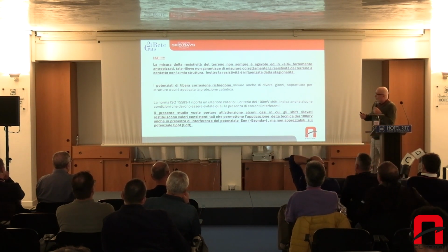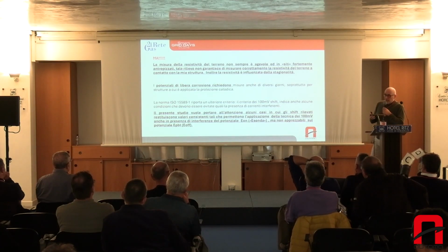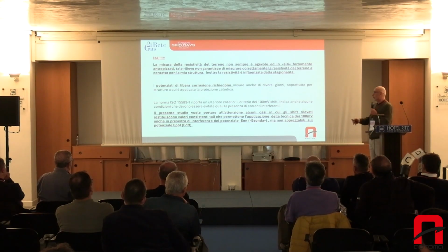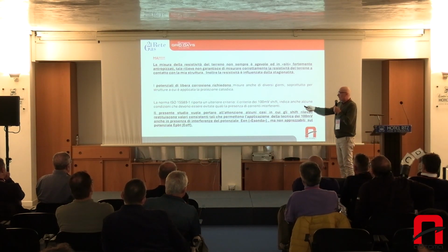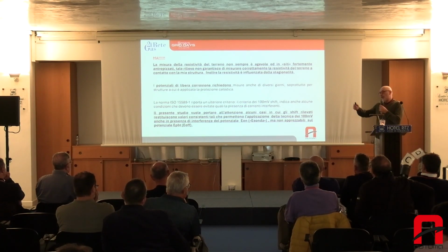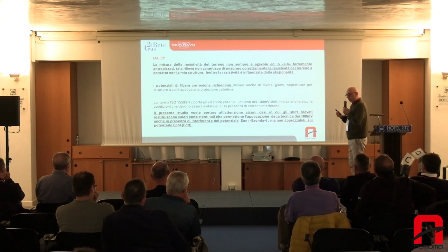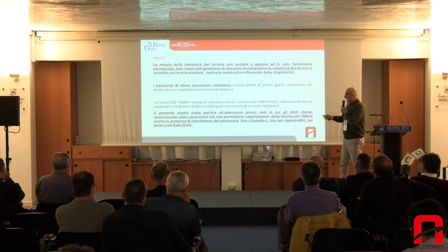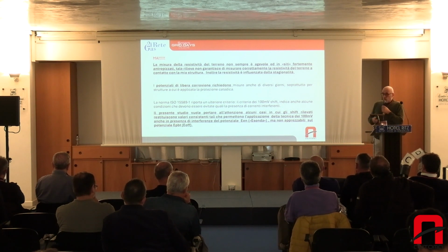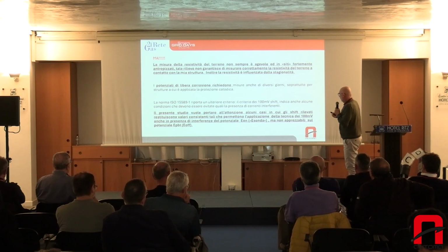And some technical expert needs to assess them. And then the standard says that in case you cannot achieve the minus 0.85, you could use the 100 millivolt shift criteria. But it's important that there is no interference on your pipe.